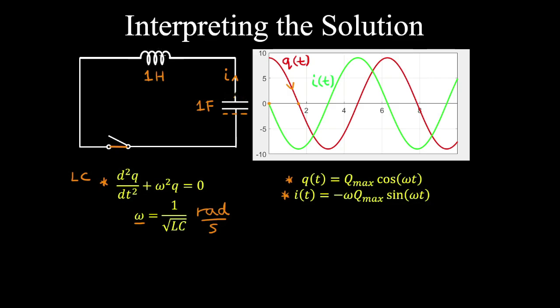and the magnetic field in the inductor has the maximum amount of energy. So remember, the energy stored in the inductor is 1/2 by the inductance by the square of the current. So at this point, the inductor is behaving like a wire. So current continues to flow through it, and the capacitor is getting charged at this stage.